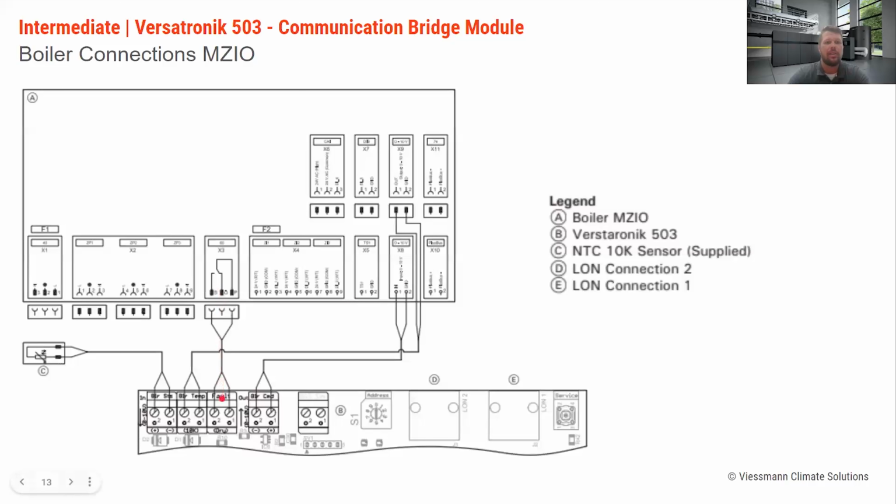We do have a fault message output, so that fault message output is going to be wired to S and P. I'll have to check with this, but we are going to wire to this plug 66. So when we're at address 1706 and we're going to engage the 0 to 10 volt, we're also going to tell the unit that it has a fault message output, where we would say, I want fault message output and temperature demand would be your option at address 1706.